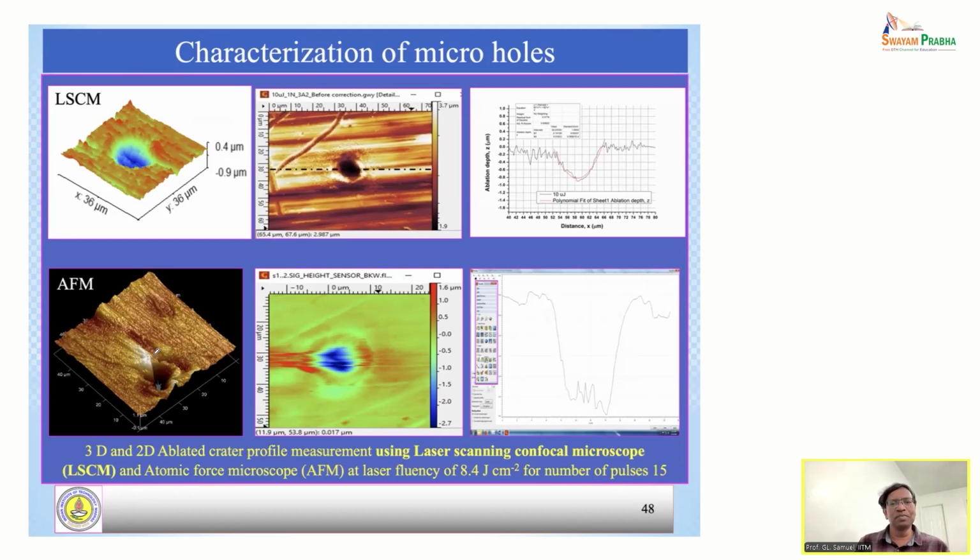The probe comes very close to the material, and there will be either attractive or repulsive forces, and based on how the stylus is moving, in a few sub micrometers, nanometers, a small movement will be captured, then magnified by a mirror reflector, and then we can reconstruct the shape of the profile of the surface. So this is AFM, the atomic force microscope.